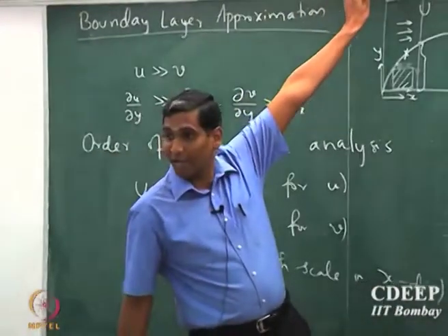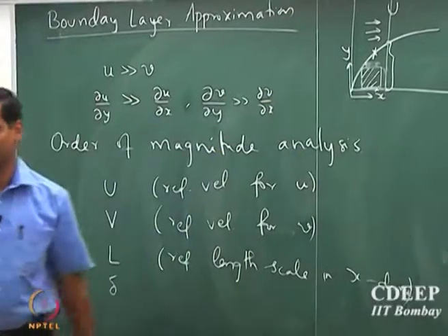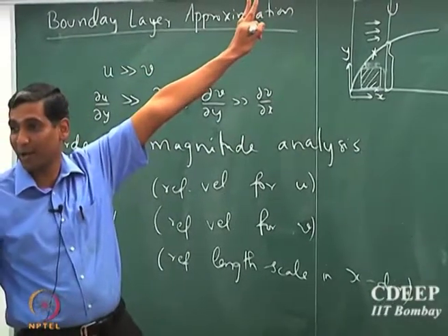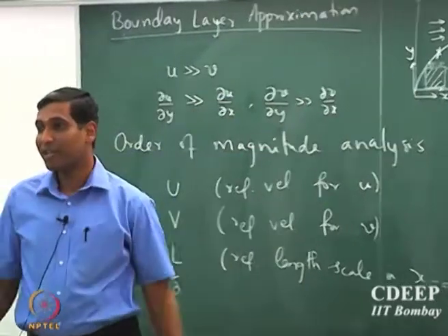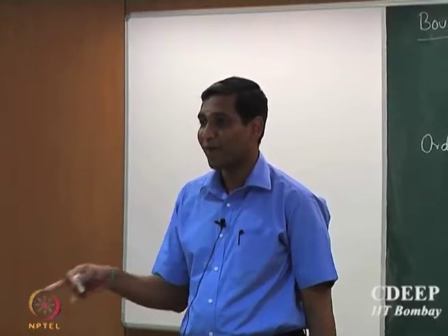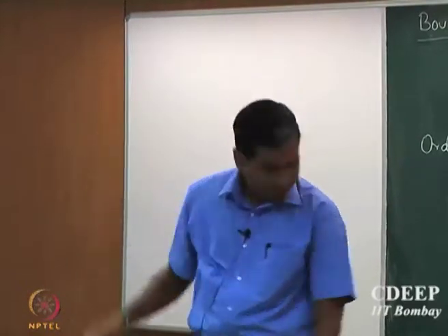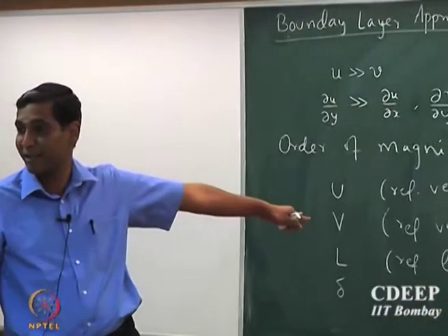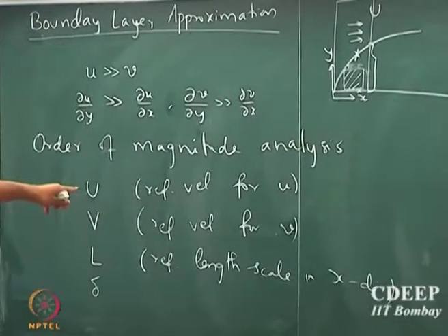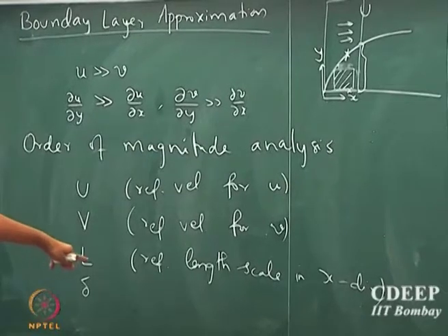Well outside the boundary layer? No, it will not be. Well outside the boundary layer, you will not have mass flux, which means that the fluid is no more moving in the x direction. You're going to have a net pressure gradient in the y direction. In fact, you're going to see from order of magnitude analysis that the net pressure gradient in the y direction has to be 0. We'll see that in a short while.